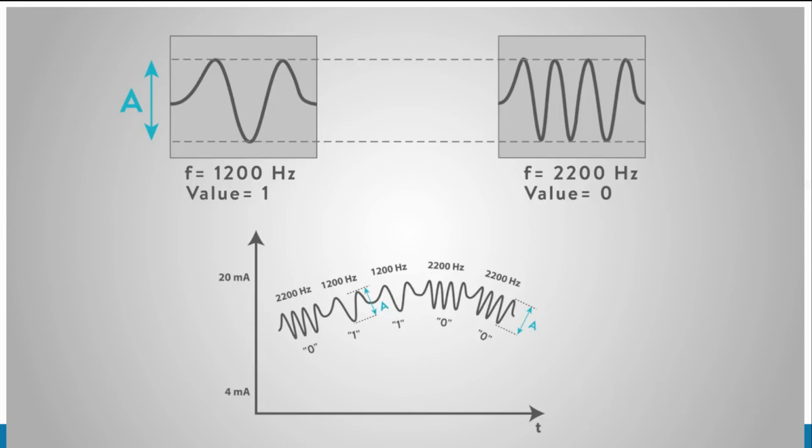The net effect of the sine wave is then 0. So, the analog value of the sensor measurement data is not affected by the Hart signal, just as a telephone voice conversation is not affected by the caller ID signal using the same Bell 202 protocol.